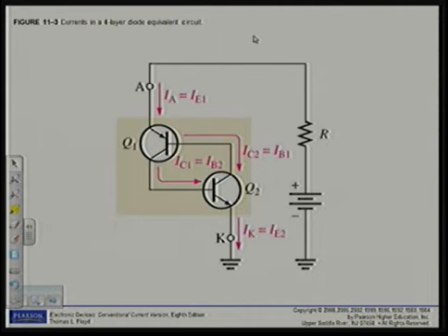The operation of the 4-layer diode may seem unusual because when it is forward biased, it can essentially act as an open switch. There is a region of forward bias called the forward blocking region, in which the device has a very high forward resistance, ideally open, and it is in the off state. The forward blocking region exists from VAK equal to 0 up to a value called the forward breakover voltage, if you can recall from the characteristic curve that I've shown you. But we will have a look at it again.